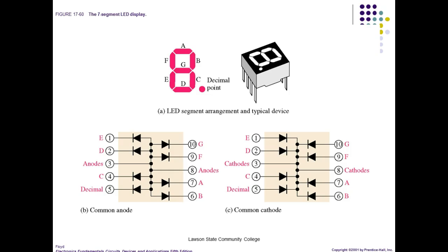7-segment displays, we have 2 types. We have what we call common cathode and common anode. So common anode, what we would do is we would put power on pins 3 or 8. Now, normally these things are set. You don't have to put power on both those pins. These guys are usually placed on printed circuit boards, and since they have pins available, they put power coming out on both sides, so you can power it on either side. And that way it may be easier to power. And y'all see common anode.